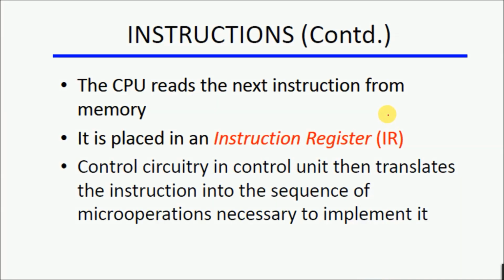So an instruction is executed as follows: the CPU reads the first instruction from the memory at address 0 and moves it to a special function register called the instruction register. The instruction register has some control circuitry and decoding circuitry hardwired to it, and that instruction is decoded and the respective control signals are generated to control different registers and different modules of that computer.